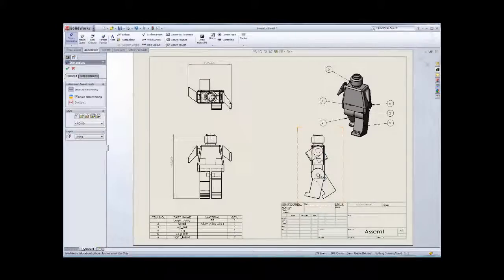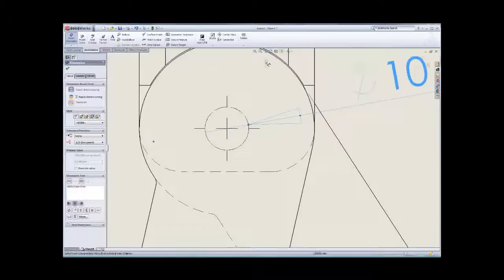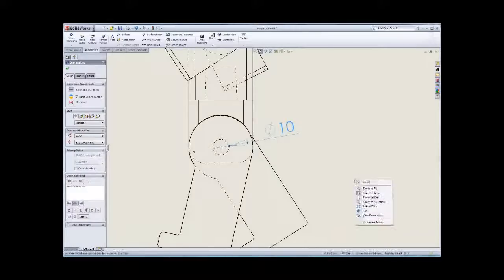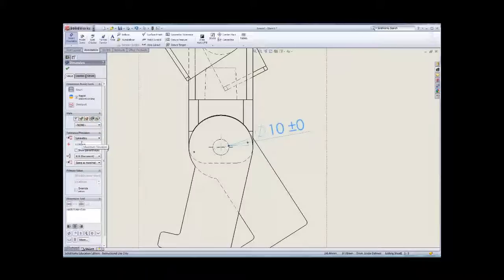And then when you make the smart dimension for that hole, you can just zoom to the area and then click here, and then you can see the diameter 10. And then because you learned some of the tolerance before, when you have the tolerance, you can just make it here, because you have maybe the symmetric tolerance, maybe the 0.02, because our caliper can measure that, so you can just make some of the tolerance here.